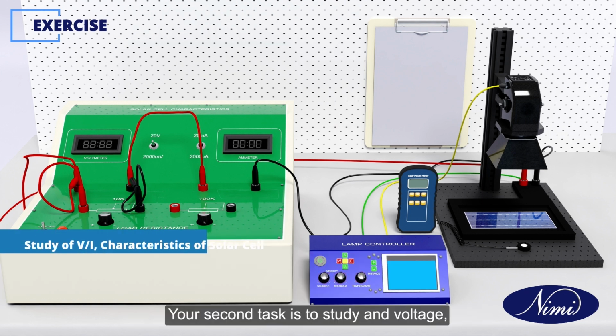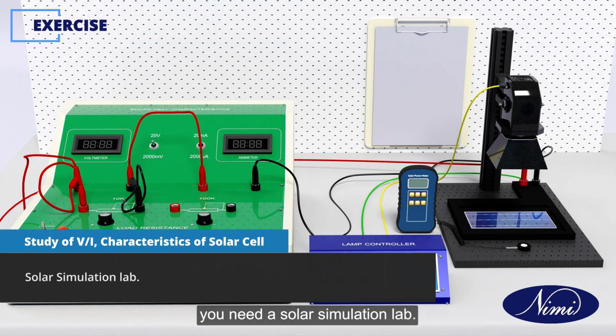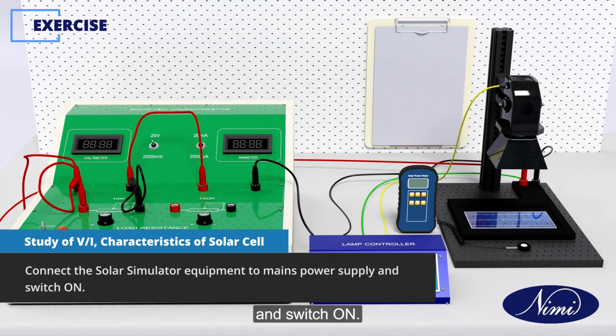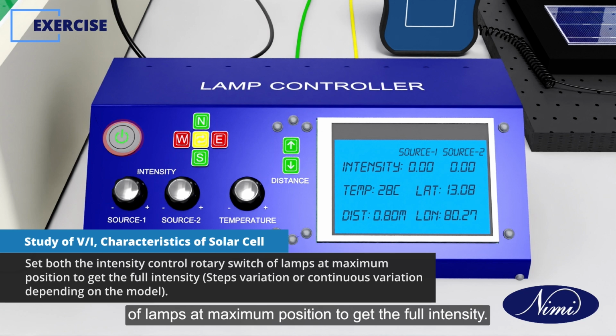Your second task is to study the voltage, current and characteristics of a solar cell. To perform this task, you need a solar simulation lab. Connect the solar simulator equipment to the mains power supply and switch on. Set the intensity control rotary switch of the lamps at maximum position to get the full intensity.